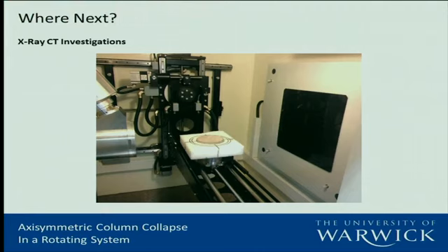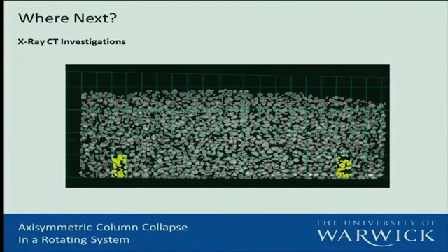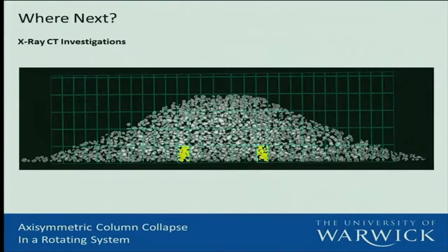To the left, we've got the X-ray head, which is going to fire X-rays. Some will be absorbed by the pile and then collected by the computer. We can see a 3D structure and look all the way through the pile. What I'm going to investigate is the porosity of the pile and compare this pre and post collapse. It should show where the failure envelope is going to be, and we should also get some nice gradient scalings of porosity, which will indicate parts of the collapse.